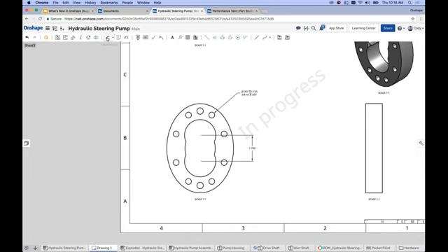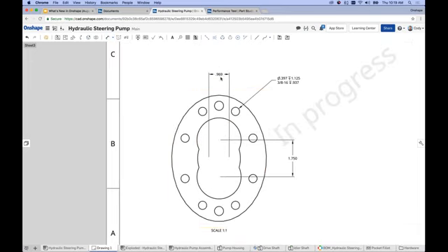So let me give you an example. Let's say that I'm placing a dimension at the center of these arcs, and I later decide, you know what, I want to move that dimension. By default, when you select 2 points, or 2 arcs, I should say, it dimensions to the center point of those arcs. But you can grab and drag.